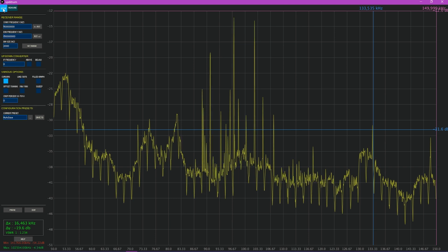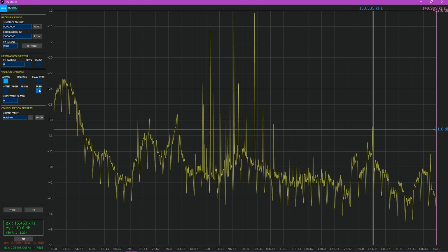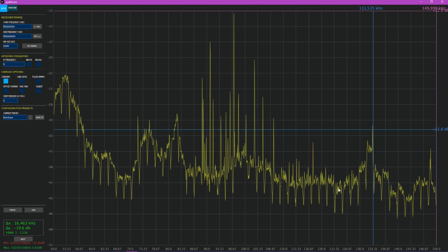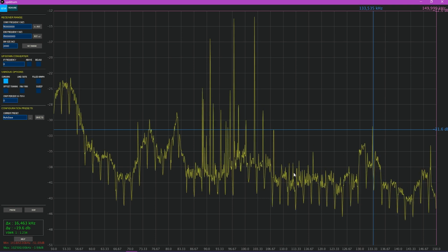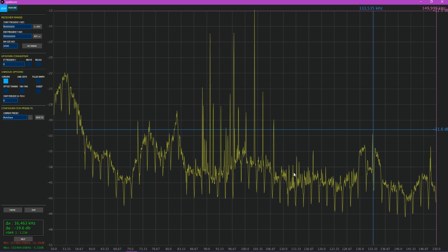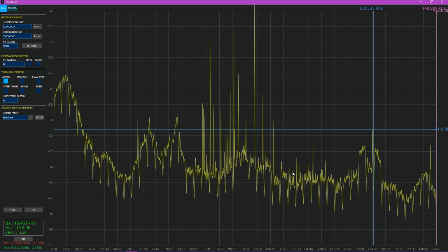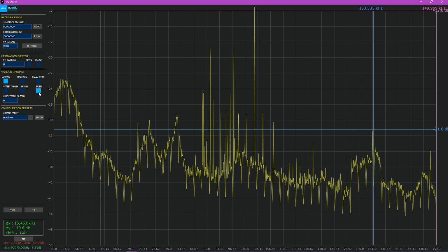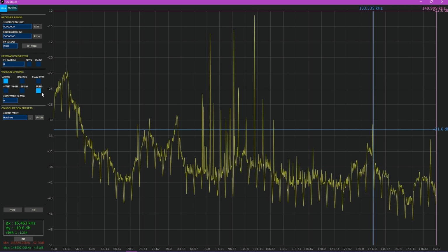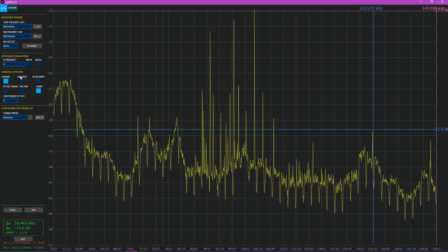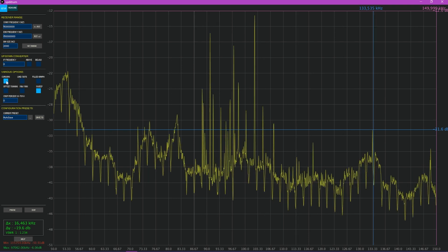If we go back over to setup, generally you want to have the sweep option on. I think because we were in relative mode, it decided to continue sweeping. The software is a little odd with some bugs like this, but typically you're only going to get one sweep unless you have the sweep mode turned on. So I would recommend that we go ahead and hit sweep just because we're measuring something passively, and we're also going to go ahead and turn off the cursors.